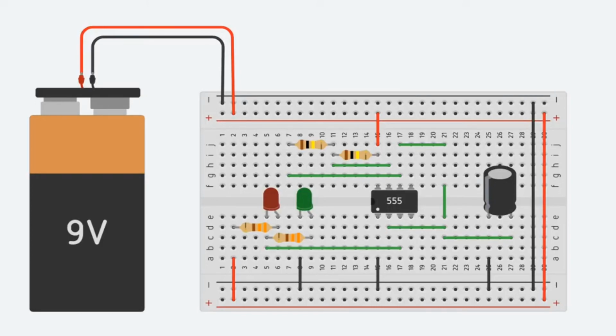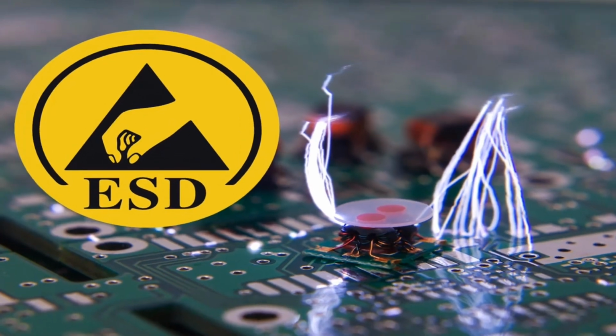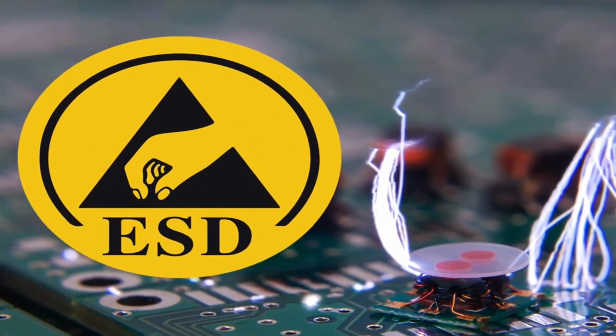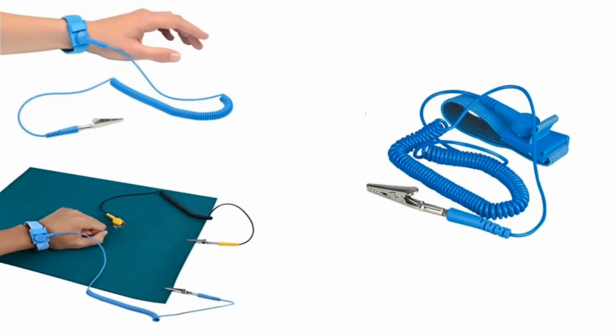Since ICs are very sensitive to static electricity, they should be handled in accordance with electrostatic discharge, or ESD, techniques. When we touch them directly with our hands, they can deteriorate quickly due to the static electricity in our body. This electric discharge can cause damage to electrical tools and components, and, in some cases, actually cause equipment failures.